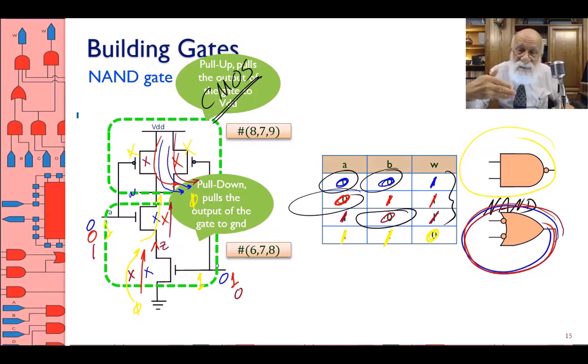And this stays with us forever, for as long as we are dealing with CMOS. Structurally, they are complementary. NMOS is always at the bottom, PMOS is always at the top. What we have in parallel below, we have serial up, or we have a combination, as we will be showing. This situation always gives us complementary CMOS structures.